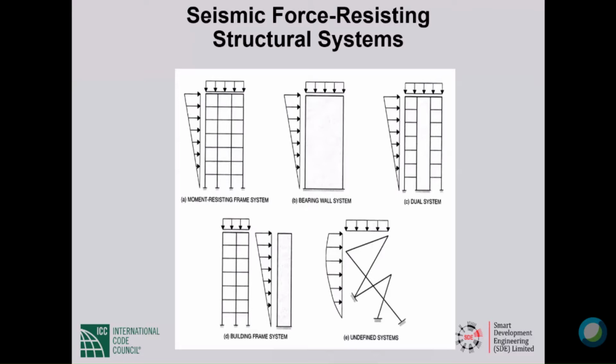If you do a proper interactive analysis of the combined structural system under lateral forces, you will see that near the bottom of the structure, almost the entire base shear goes to the shear walls with nothing carried by the frames. And as you go up, the frames pick up more and more with the shear walls unloading on the frames. Okay. You have to design the frames and the shear walls on the basis of that interactive analysis. They will take different percentages of story shear on the different floor levels.